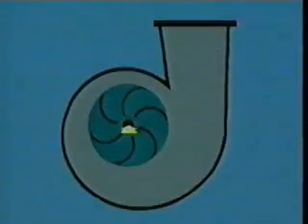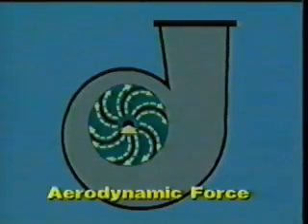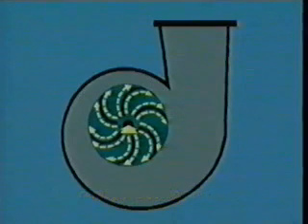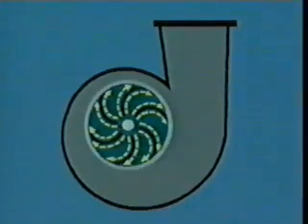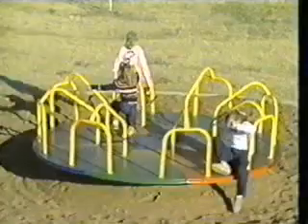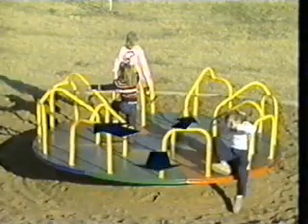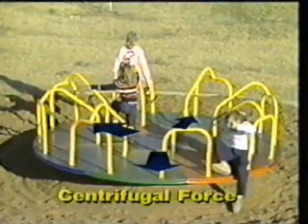When gas enters the compressor, several forces are acting on the moving gas. One of these forces is aerodynamic. An aerodynamic force is the same force that causes an airplane wing to lift as it moves through the air. This lifting force helps to move the gas from low pressure at the eye of the impeller to high pressure at the outer edge. Another of these forces is centrifugal force.